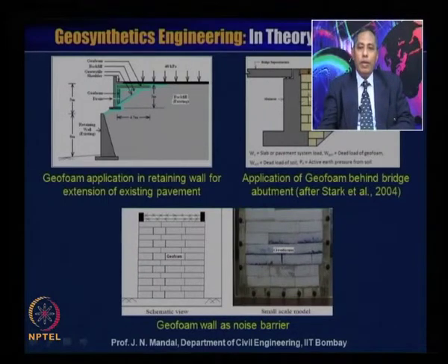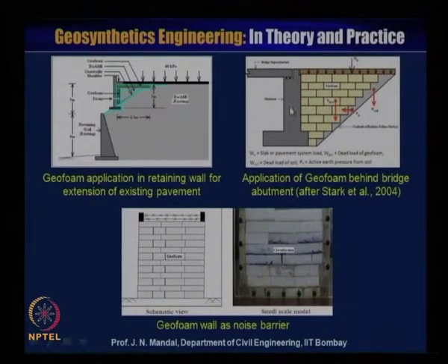Now here is the application of geofoam behind the bridge abutment after Stark et al. 2004, where this is the weight of the pavement system, also what we call the dead load of the geofoam. If there is any seismic aspect, that you can also take into consideration, also the dead load of the soil, and also there will be the active earth pressure. So all this has also been considered for the design.